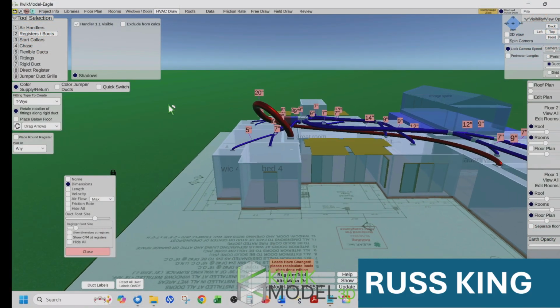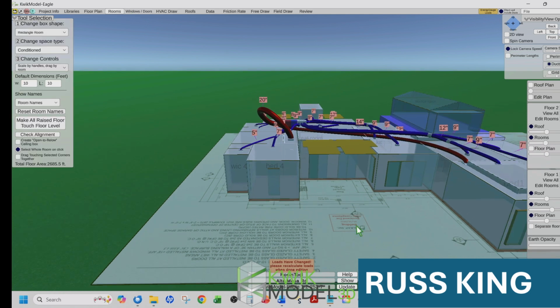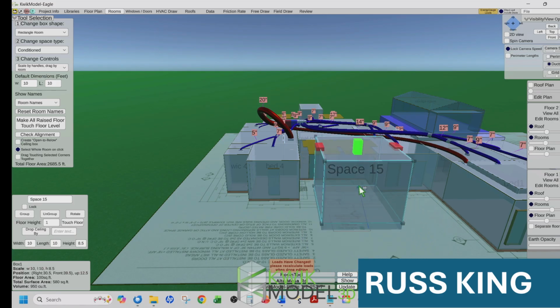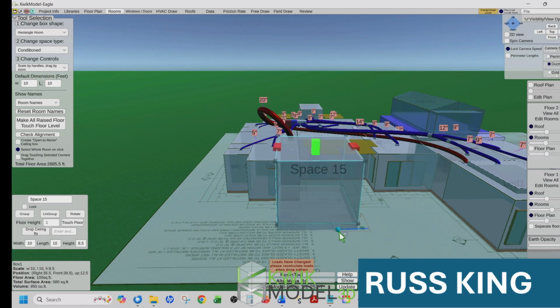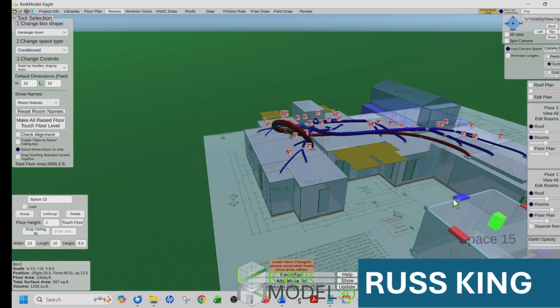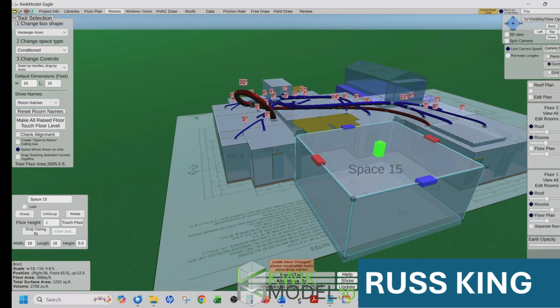If you start from scratch, let me just show you really quick how you place a room. That's one of the cool things. You just alt-click and it places a box like this, and that happens to be on the 2nd floor. You can see the box is scalable, and we have a lot of different shapes you can use. You just build a house out of these boxes, and by placing one box, I've just drawn 4 walls, a ceiling, and a floor with one click.